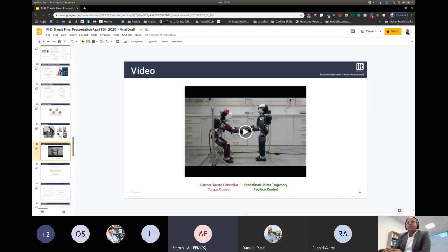So you can, for example, define a certain force reference and look at whether the external force is following the force reference or not, include this in the state error, and then by controlling as input the derivative of the input range, would that result in an automatic exploitation of the external perceived range when it's a helpful interaction or when it goes in the right direction? Would it be equivalent to what is done in the helpful interaction paradigm?